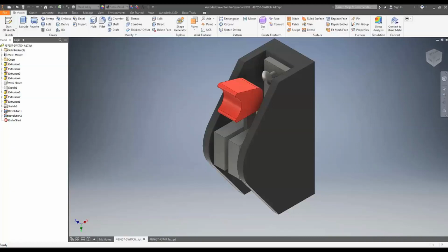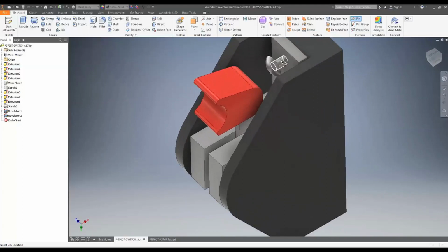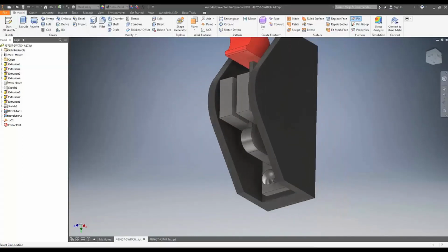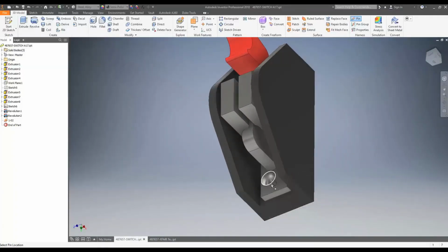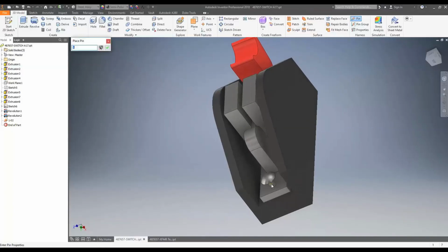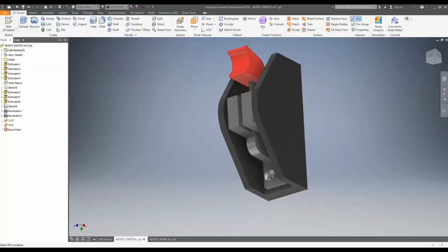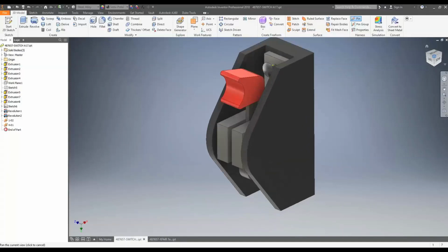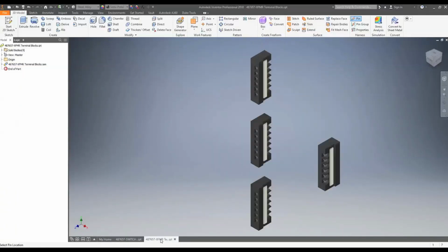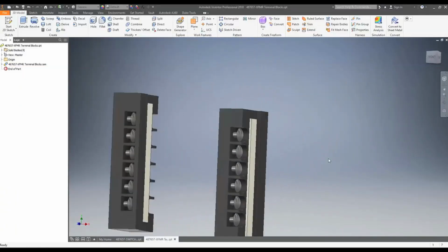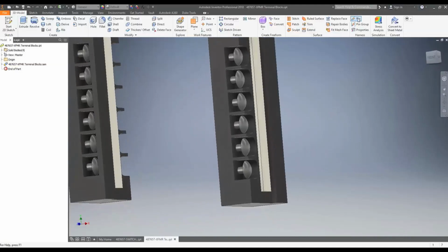Initially, I wanted to make sure to label the electrical component pin locations identical to what they are called in AutoCAD. This is to avoid the step later in which we would have to assign them. And it just makes sense instead of naming them something that is meaningless to the P&C guys. Here I place the pins for one of the panel switches. And then the pins for the terminal blocks in the control box.